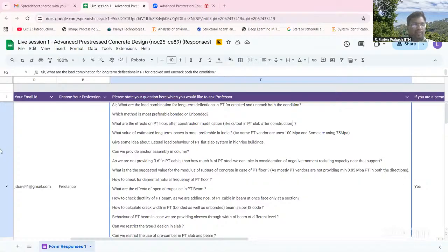I mean, with a steel beam, again, the installation you have to design properly. If the building is already occupied, then it becomes a little difficult. Let's say you're doing it on the third floor or fourth floor, taking the members to that floor in a building which is partially occupied becomes difficult.